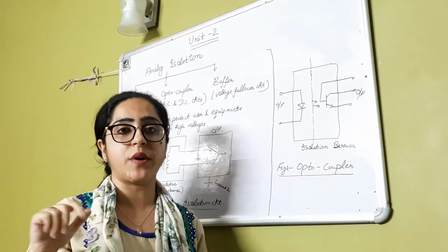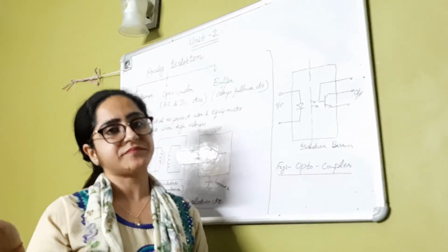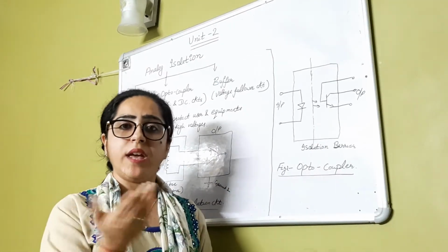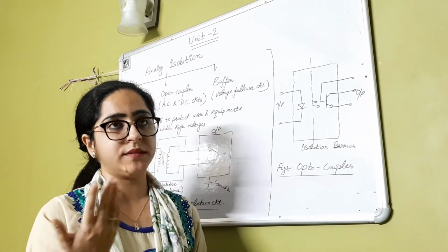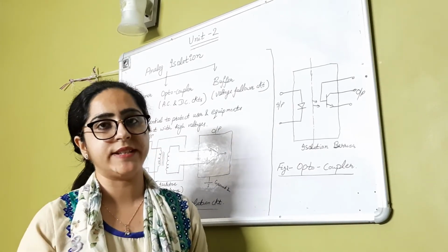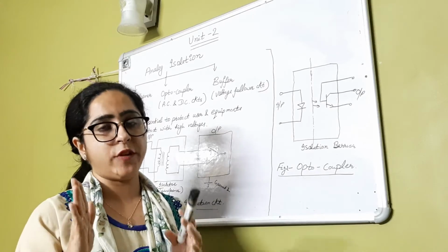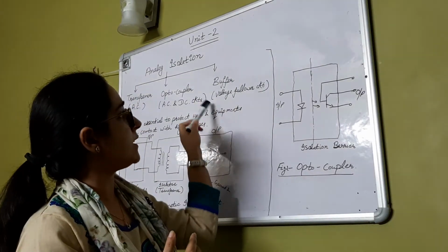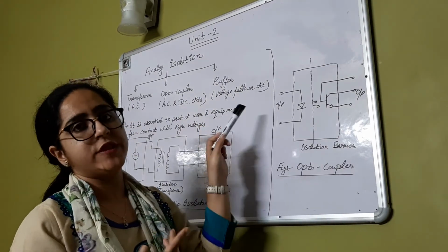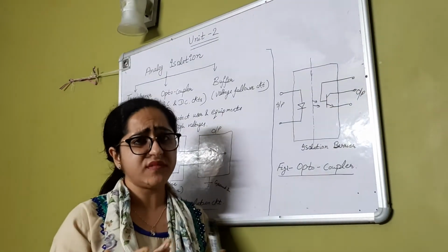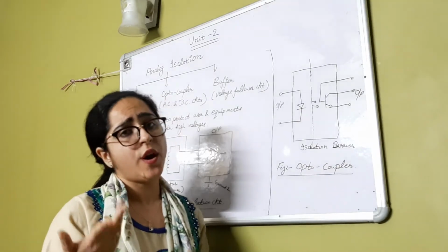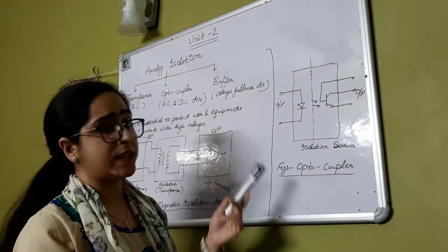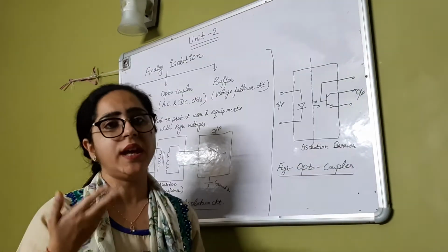Once the conversion process is over, the next value will come through the sample and hold circuit to the ADC. So for ADC isolation, we go for the isolation amplifier or the voltage follower circuit, which is nothing but a differential amplifier also, where the output voltage follows the input voltage.